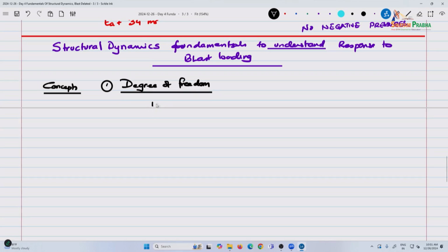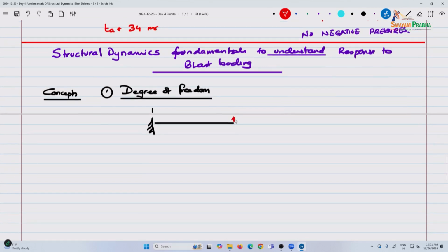So in general, if I look at a beam, as we've seen in finite elements, you have degrees of freedom associated with ux, uy and uz, and also you have theta z, then theta x, and this is theta y. So general is 6 degrees of freedom per node, and it depends on where you look at it from a structural perspective.